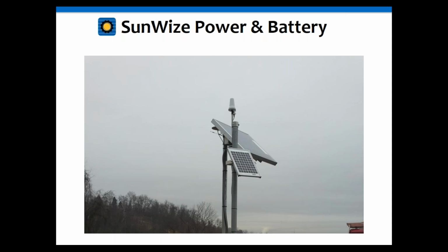Okay, I just want to show an example of two different solar modules and two different poles at a site location that I was at recently. The first thing I noticed, if you take a quick glance, is that the solar modules are not in the same plane, so somebody's not facing south correctly. These are two completely different installations on the same site, so somebody got it right and somebody didn't. If you see something like that, it's a quick indication that somebody's not right. You might want to pull out your compass and double check who's wrong.